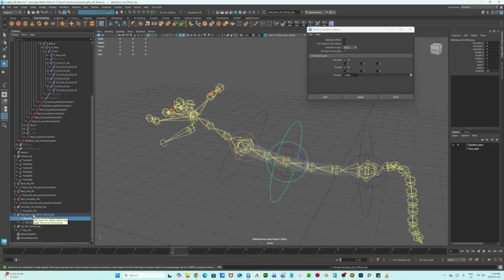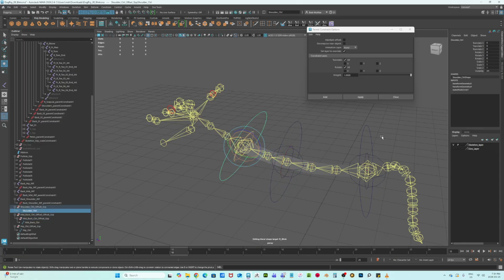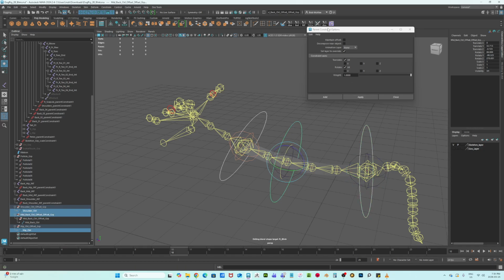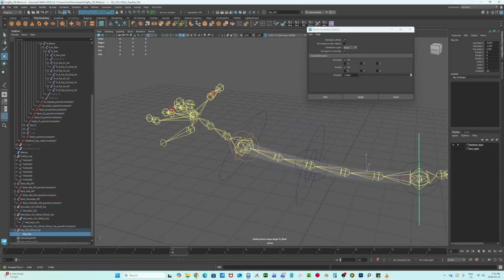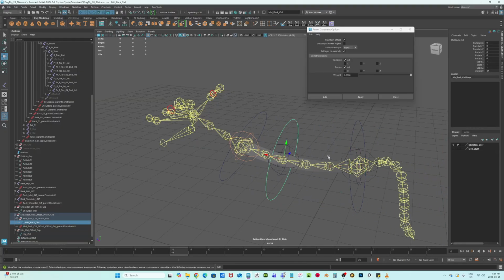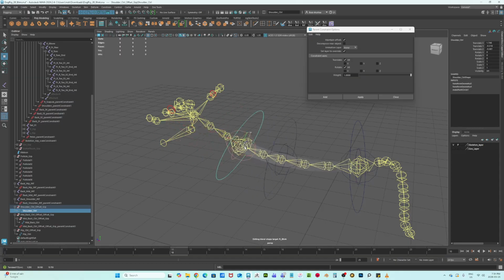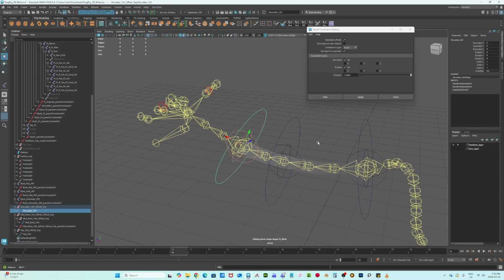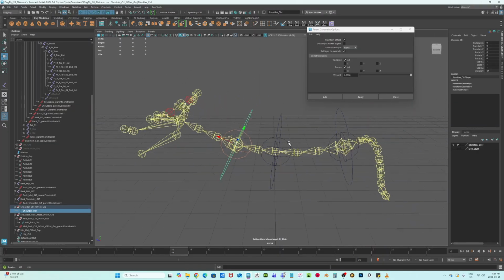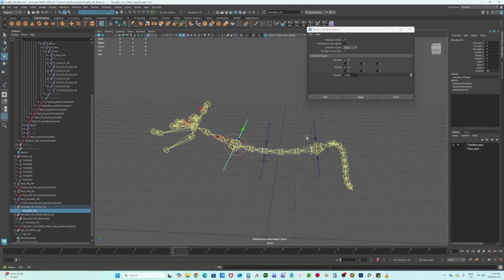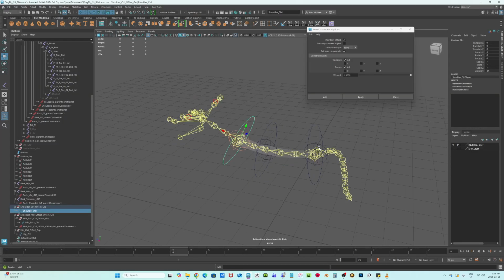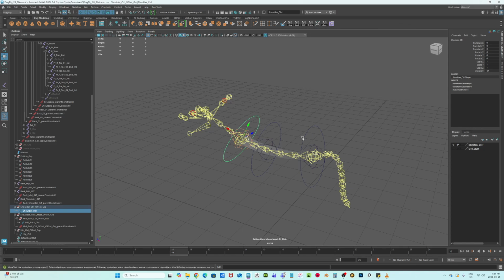And if I select this one first, then this one, and I grab that little offset, offset group, and I have parent constraint, I'm going to turn maintain offset on, and I'll hit apply. And now when I grab this and I move it, we still got control. This thing is following along, and if I grab this one and move it, okay, there's some other constraints we have in the legs and stuff like that that I probably need to delete off this file. But there you go, I got all my back controls. I might want to consider some other type of control as well as these.